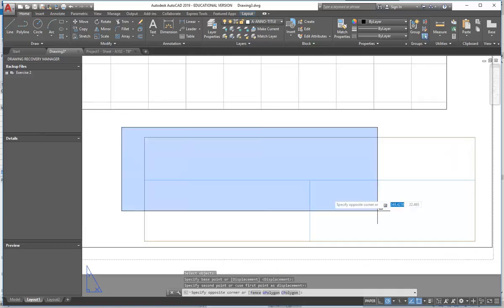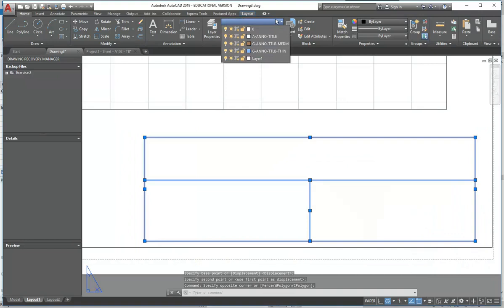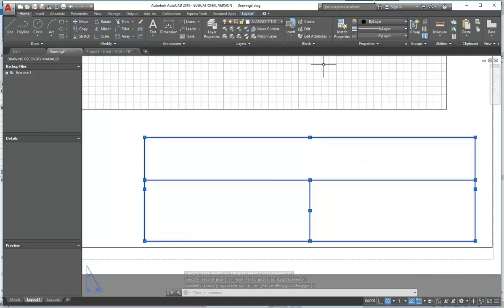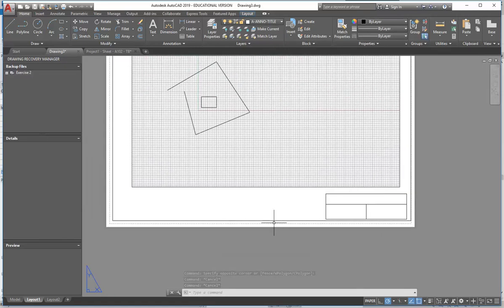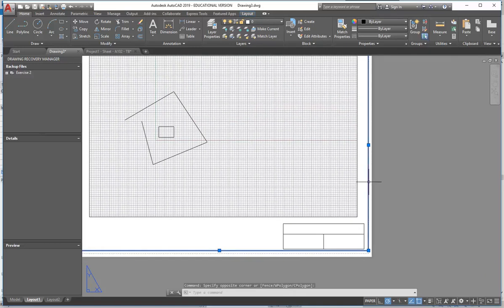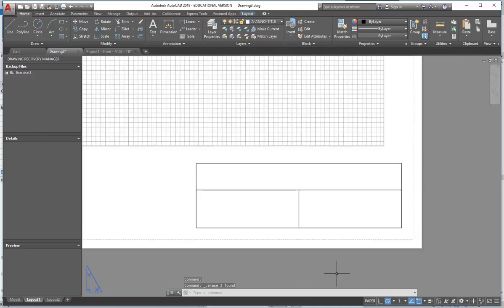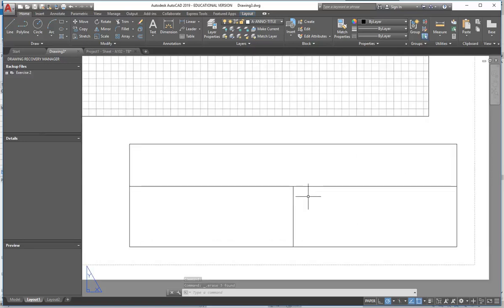So I've got my lines, they're exploded, and I can then change them all to the same layer. Now watch out for these options here, where you've got properties. Make sure all of those are on by layer, if you want to be using the layers, colours, and the other things that you're setting, and you do. So I've got my lines, but I'm sure you could all do that. And so then, well, I don't even really need these lines that I started with before, but I know that I'm inside them, and that's the main thing. And then, last thing I want to show you, and I'll give you hopefully plenty of time to try these, is text. How to get it the right size.